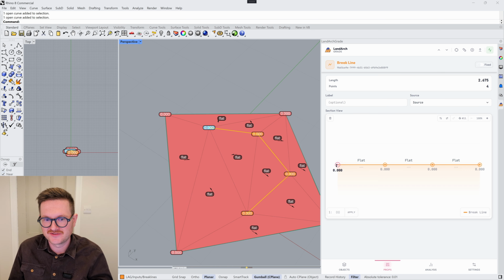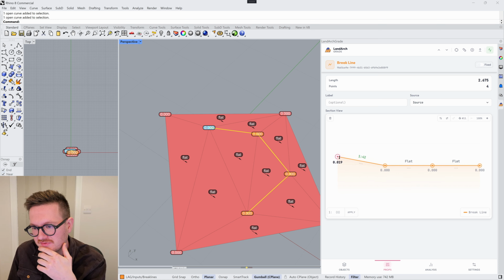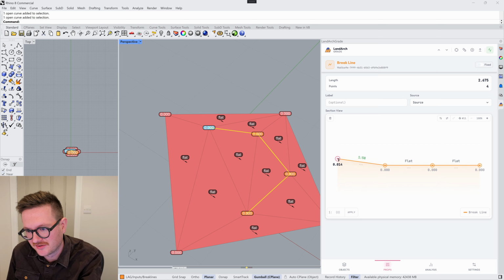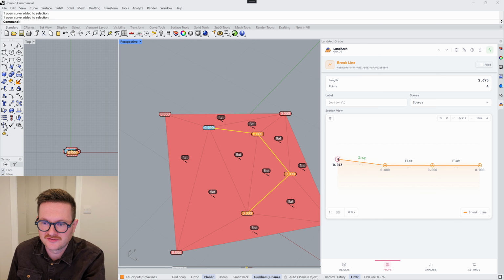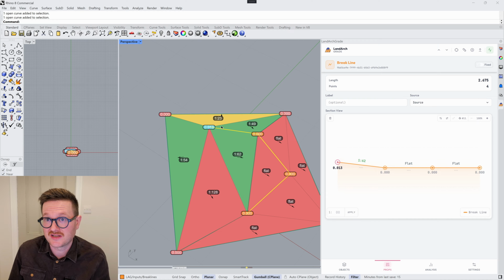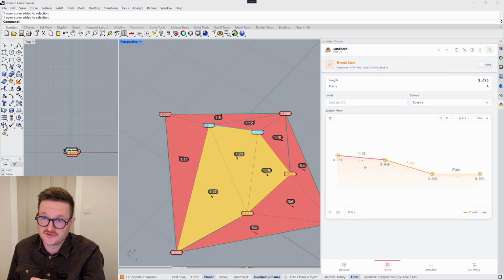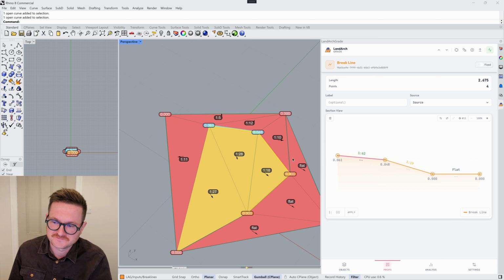What it lets you do is you can click on a node in the spot height and drag it up. And you can see while we drag it, you can see the live grade between that node and the next node. So if we wanted the 1 in 62, we drag that up and that drags that node in that curve. What we can also do is drag the entire section up as well, and that drags the two nodes up at the same time, right?